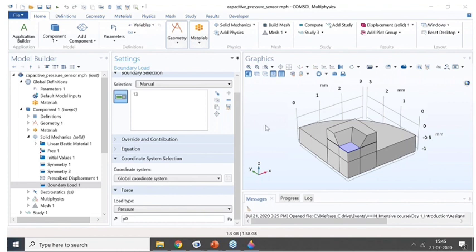Yeah, so there's one more question: how to convert 2D geometry, a 2D model, into 3D. You can convert this 2D geometry into 3D using one of the options. There are many options. One of them is extrusion that we did yesterday. Another option is rotation or revolution. Also, you can convert it in the azimuthal direction. So there are multiple ways, and in the geometry section tomorrow, you will get to know more about how to convert 2D geometry into 3D.